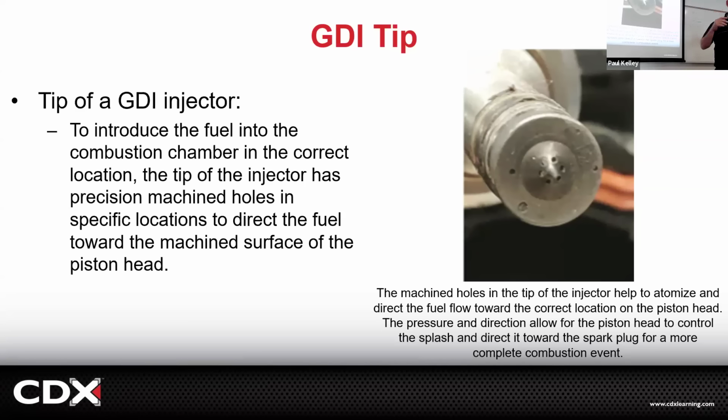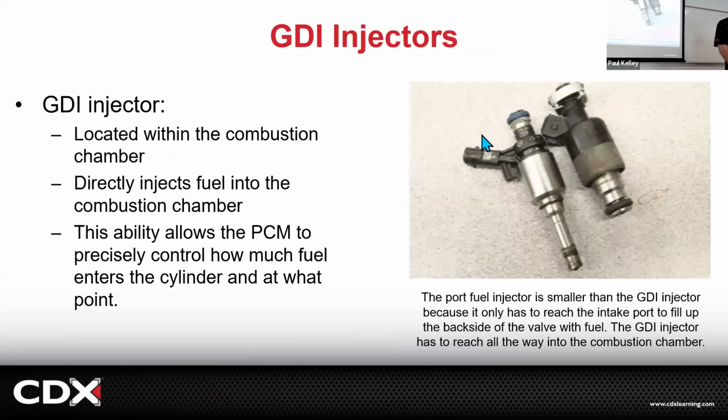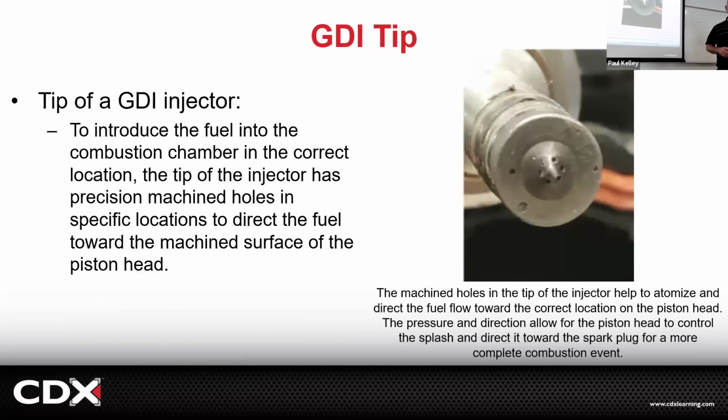So just knowing about this, the same could technically happen on a port fuel injector, but those systems were not advanced enough to know if you have one slightly dirty one and one slightly cleaner one. But these systems are. They're paying a lot of attention. They're looking at your air-fuel ratio on the oxygen sensor or the air-fuel ratio sensor, and it knows which cylinder it had fired when that airflow hit that sensor. So it can tell if there's something a little off on the cylinder. Because again, we're trying to hit a very, very low emissions number and a really, really high fuel economy number.